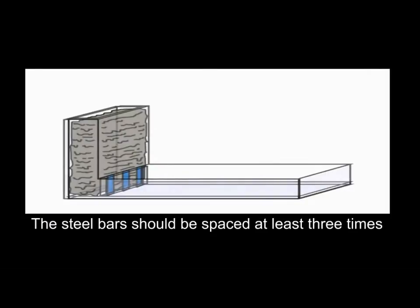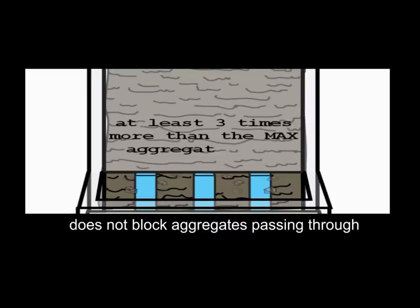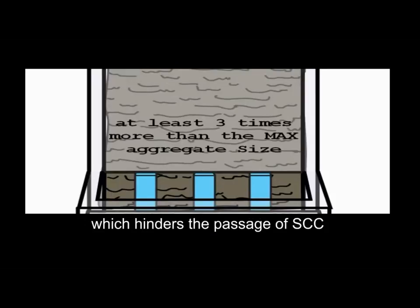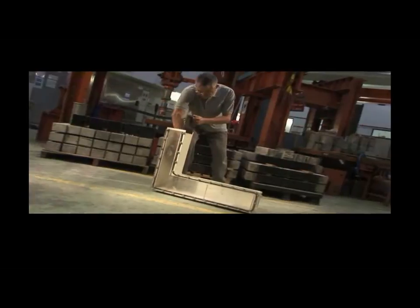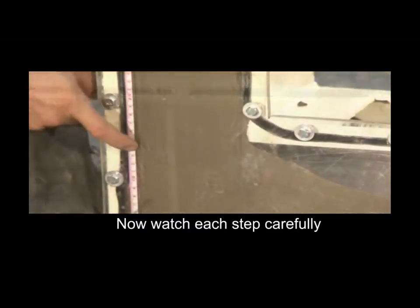The steel bars should be spaced at least 3 times more than the maximum aggregate size to make sure the bar spacing does not block aggregates passing through. These bars serve to simulate reinforcements in actual site condition, which hinders the passage of SCC. There are 3 steps to follow in the test. The first step is preparation. The second step is molding. And the last step is measurement. Now watch each step carefully.